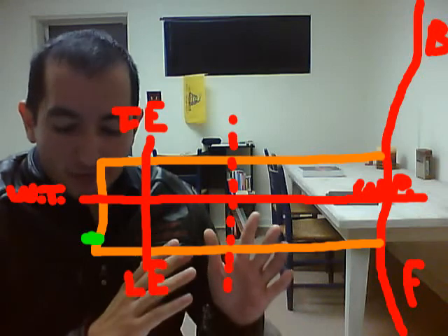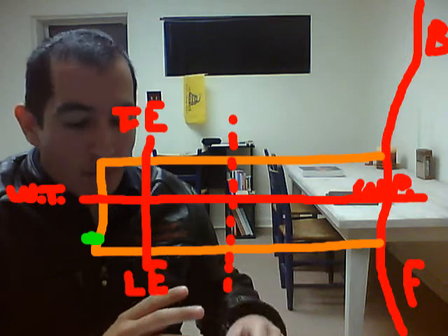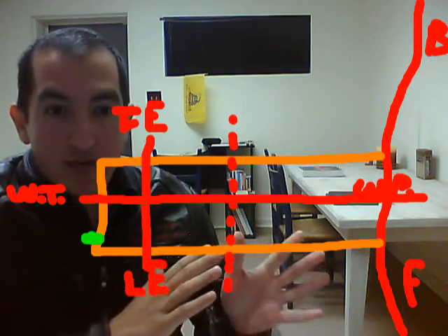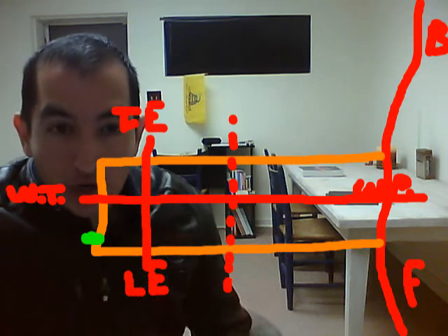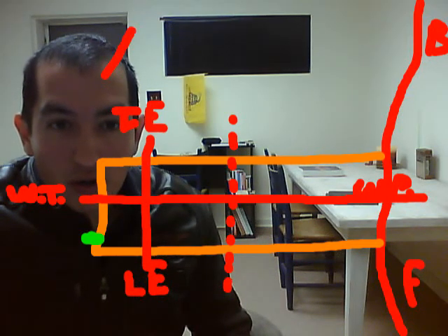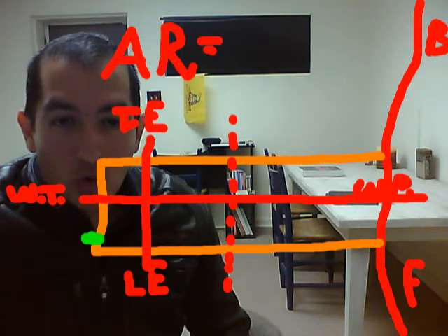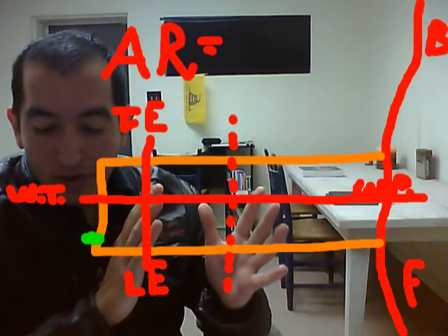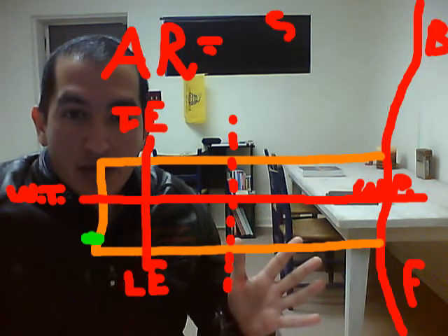Now, of course, this is when you start talking about your aspect ratio. And if you remember from your lift equation, aspect ratio plays a significant factor in determining the lifting effect of the wing. Basically, your aspect ratio is the mathematical measure of your total lifting surface of the wing. And for a perfectly rectangle wing, in this case, it would be your wingspan divided by your wing chord. Okay, because that would make sense.